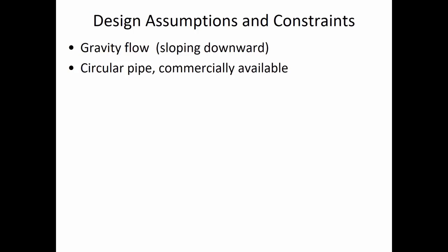They've got the water treatment plant up on the hill, and the water being up on a hill pressurizes the network. There still probably are places where they have to use pumps to get water up to the top of a tower or something. But collection networks are usually gravity flow. Pipe networks where the water is being delivered into a city are less commonly gravity flow.